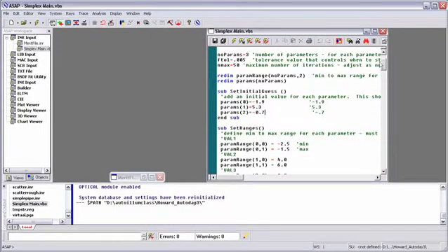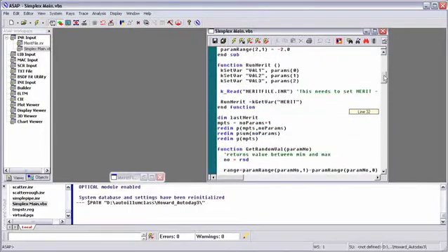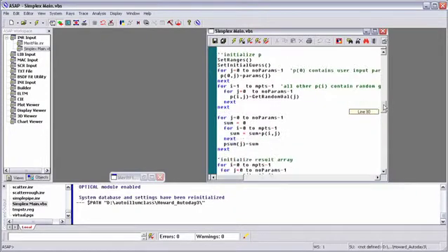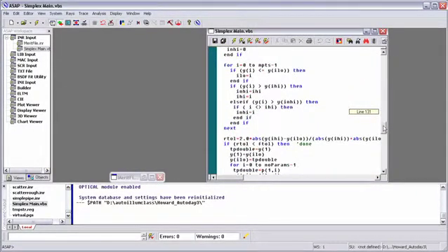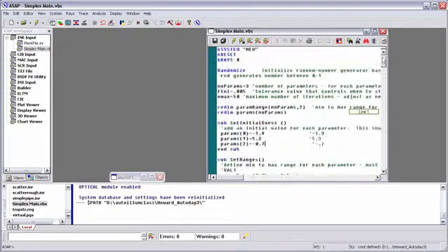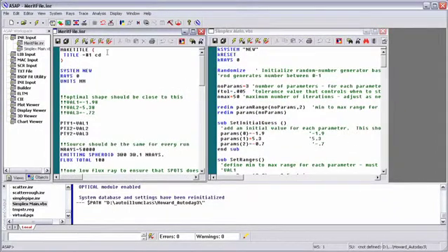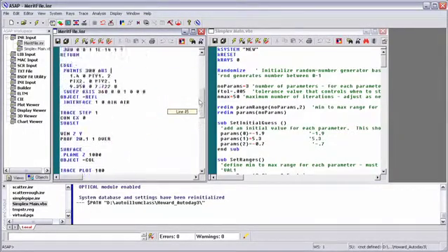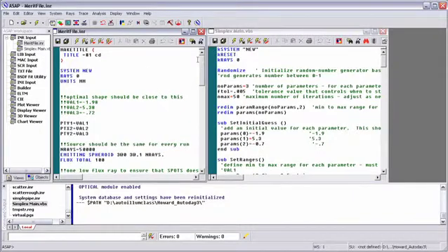For the illumination system then, we've actually written a VB script file that contains a downhill-simplex method. If you're familiar with optimizations, the downhill-simplex is one that's commonly used for illumination. So the downhill-simplex code has been written into the VB script file, and we can combine that with our ASAP file to do the analysis of the illumination system, and we're going to feed back the information from the analysis into our downhill-simplex, and the downhill-simplex is going to continue to run the ASAP analysis until we have optimized the system based on the criteria that we've given it.